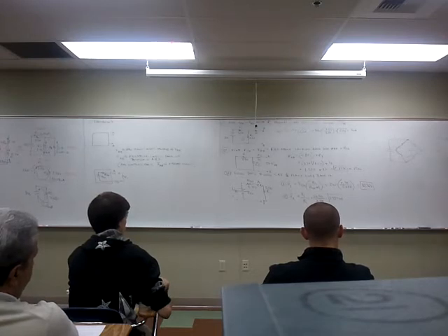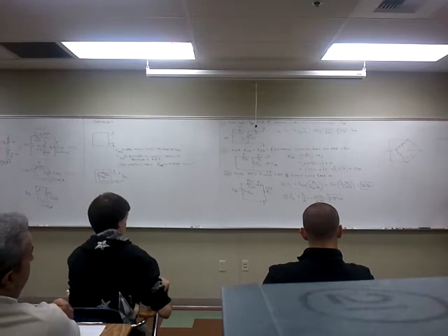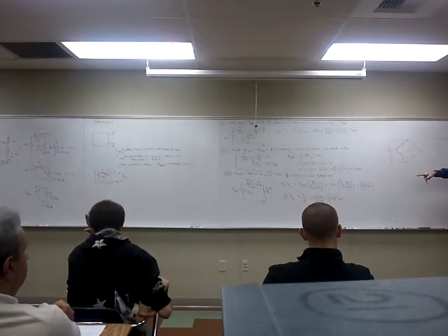And the resistance looking back into here will be just these two in parallel. If you replace that by a short, that by a short, this is A and B. You'll literally see this resistor down here, this resistor is down here, they're in parallel. You have R Norton, and you solve it like that, 2 calculations. So it's incredibly fast to solve this circuit with a thing called Norton's, which is very similar to Thevenin's.